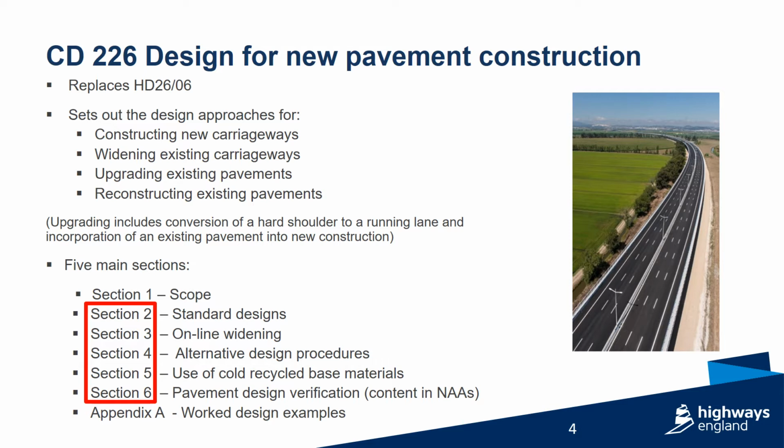CD 226 sets out the design approaches for constructing new carriageways, widening existing carriageways, upgrading existing pavements, which includes conversion of a hard shoulder to a running lane and incorporation of an existing pavement into new construction, and reconstructing existing pavements. CD 226 comprises 5 main sections.